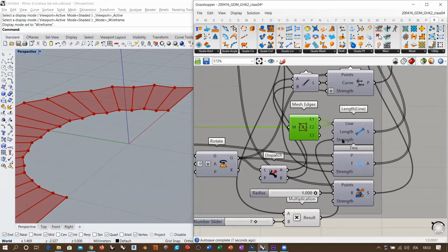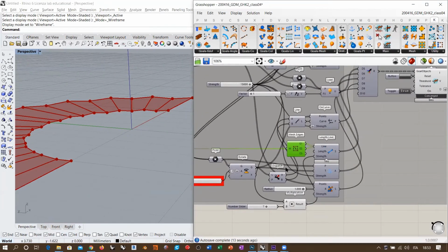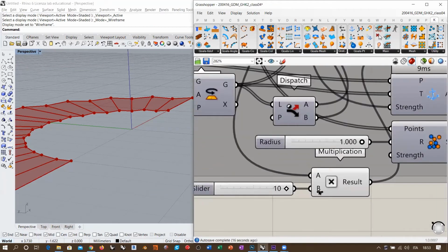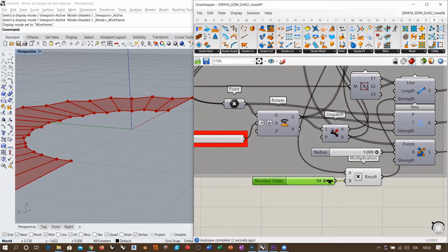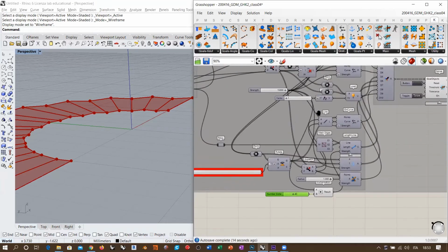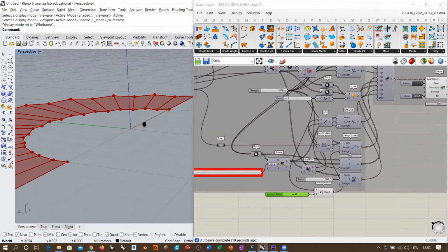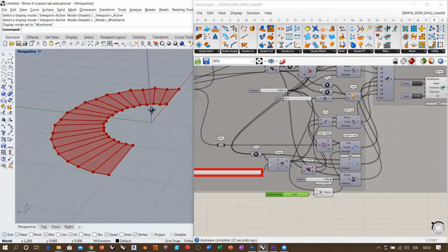Let me see. It is receiving 105,000, and still I see this kind of deformation, which is quite strong. So maybe I could also increase this a little more. Let's see what happens if I do this. By the way, you see, I'm also not using the rest length. By default, the component is using the actual rest length. So basically, applying a very light load in this case is already producing this kind of small deformation. But we can consider this an acceptable deformation.